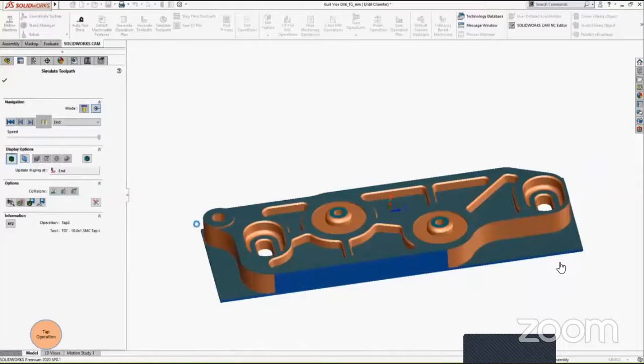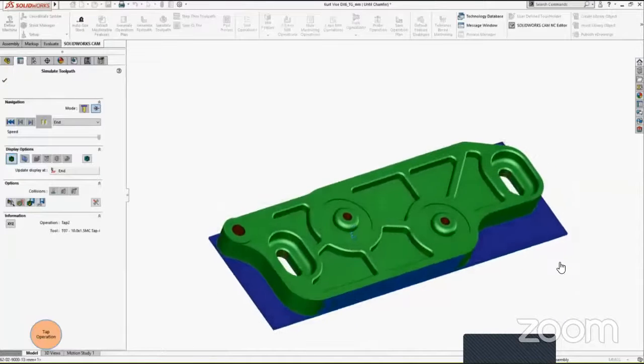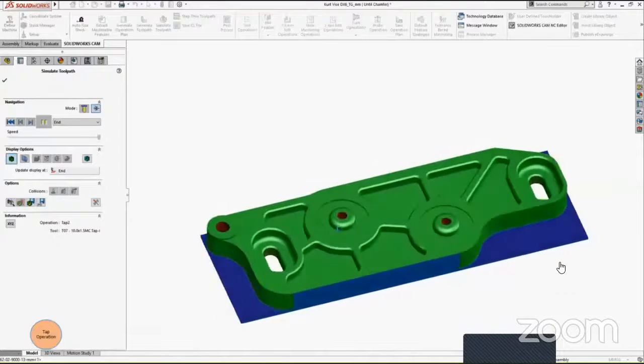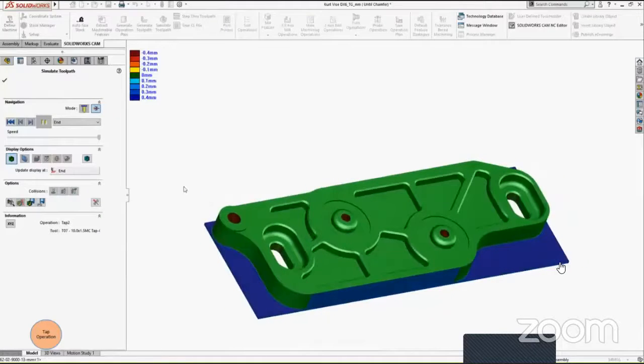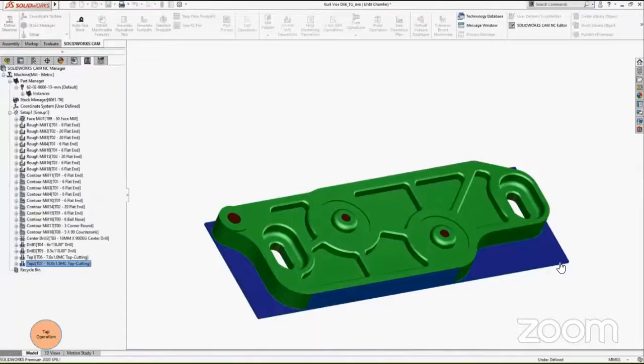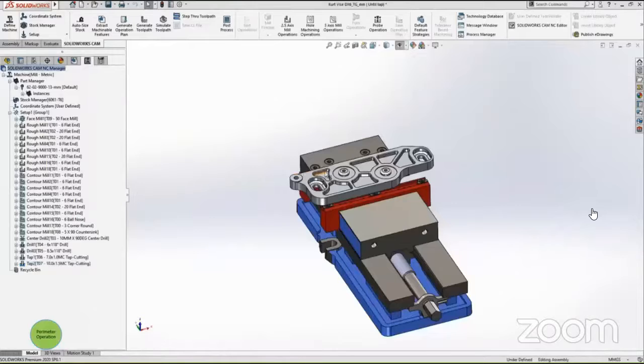All right. So everything has been done, and the holes are also tapped, and they are shown in red color. The reason they are showing in red color is because these thread holes were shown only in a visual way, and in the CAD there were no threads involved. So for such types of features, there will be some color differences. It might show in red color.